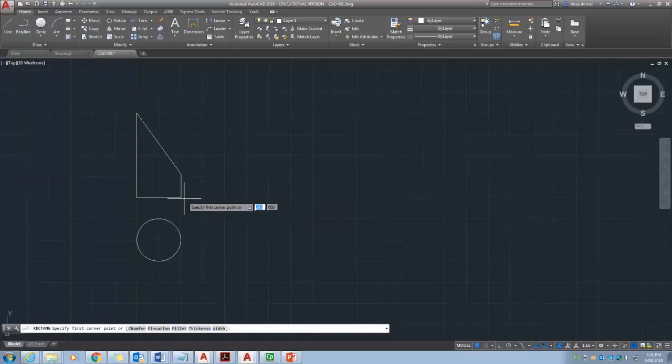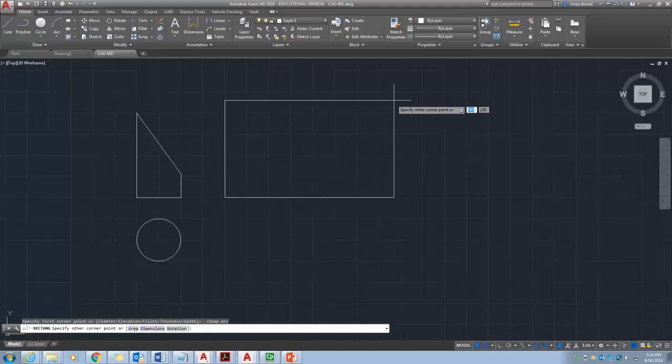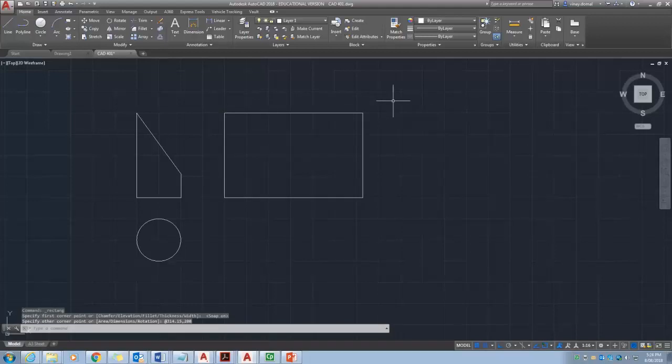Select the rectangle, snap to the intersection. You've got an inference here. If you want to use a grid again, just go to the grid and activate it. So you're going this way with the rectangle, so this should be 314.15, tab. That length should be 200. Enter 200. So that's your rectangle. The next thing would be to explode this. Type the explode command and explode this one.